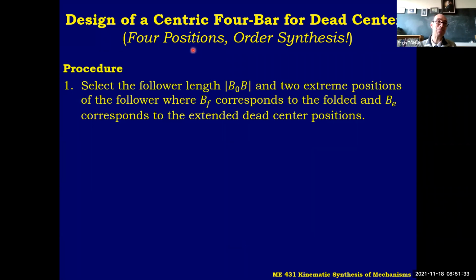Actually, this is, strictly speaking, 4-position synthesis. You have 2 dead centers at 2 positions, and you require the velocity of the follower to be 0 at those positions. So that's actually a 4-position synthesis.